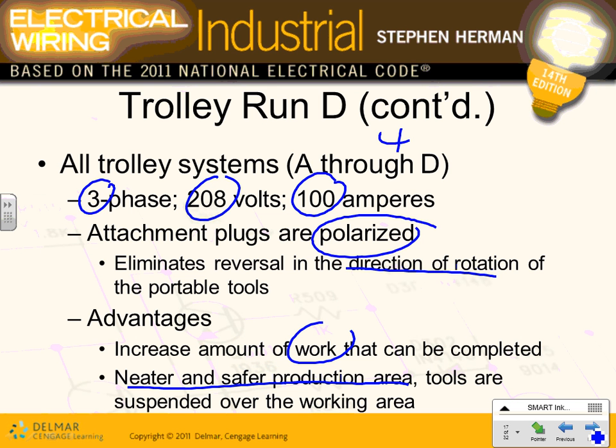Can you go higher than 100 amps? Yes, you can. But typically, guys, with all the plug-in busways, here's why it's not a good idea to go higher than 100 amp or 225 amp plug-in, for example. Do you really want to put more than 225 amp worth of loads? These are like your eggs in one basket. Do you really want to have a 1,000 amp plug-in busway? If it trips, if something happens, it could trip and shut down every single load on it.